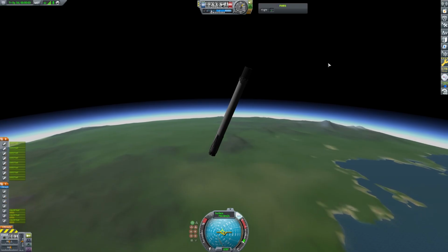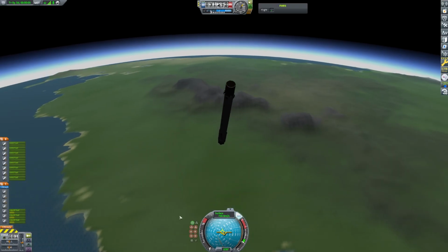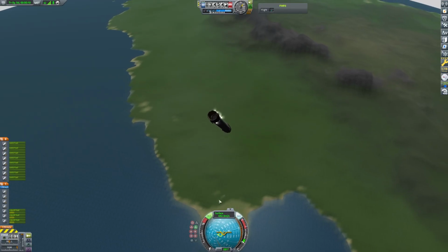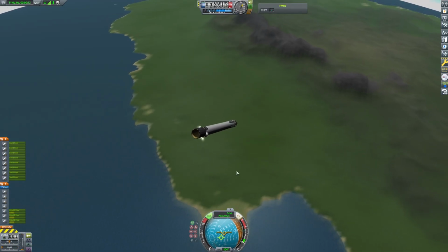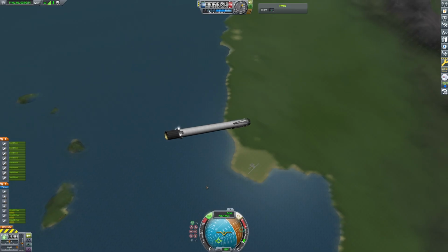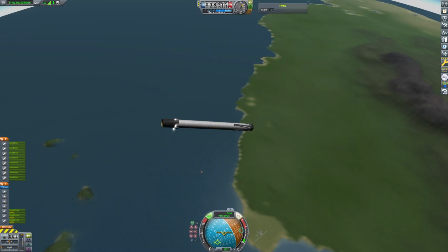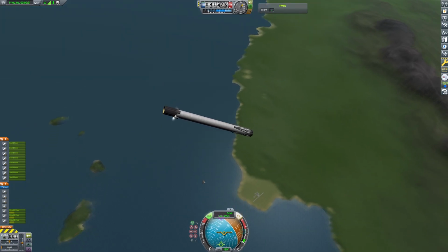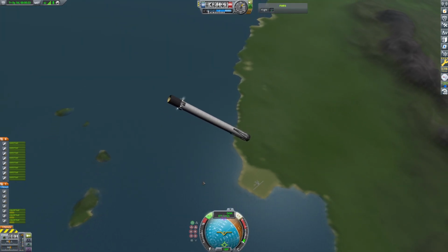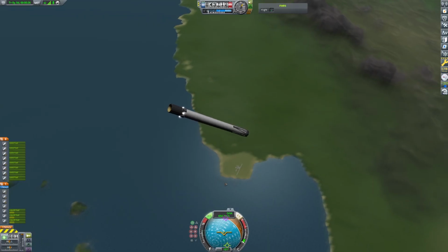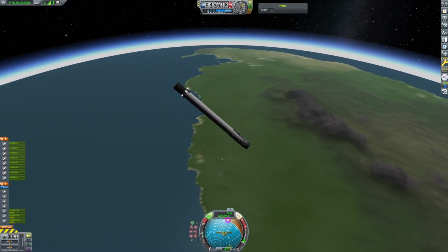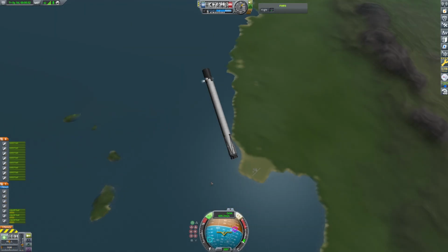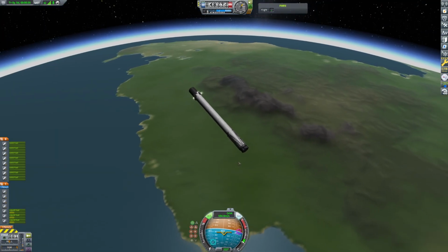So as you can see, our second stage is going to accelerate on its way, and we basically just went back in time a few minutes to simulate the first stage booster. So using our reaction control thrusters here, we're going to reorient the booster back towards the launch site before we ignite our engines for the boost back burn. Our reaction control systems use monopropellant as the fuel source, and they ignite this and combust it and use the pressure to change the orientation of the vehicle.